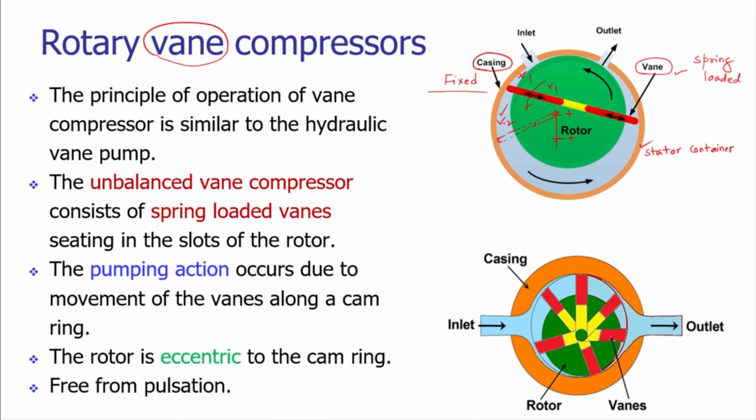As there is increase in volume from V1 to V2, the pressure is reducing. The pressure will be reduced and the ambient air will be sucked inside the cavity. During the further rotation of the rotor, the vane number 2 will push that sucked in air and take that air to the outlet wall.